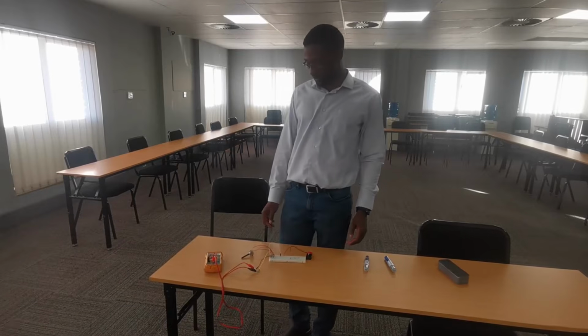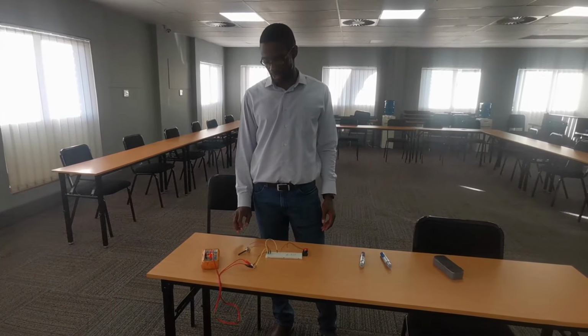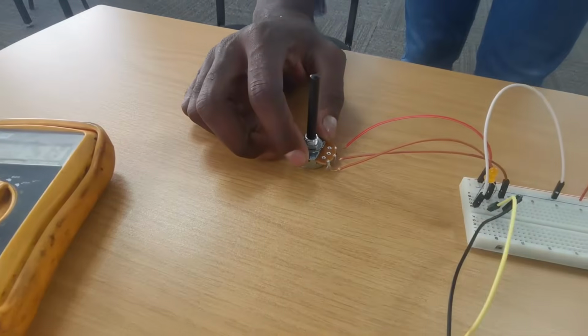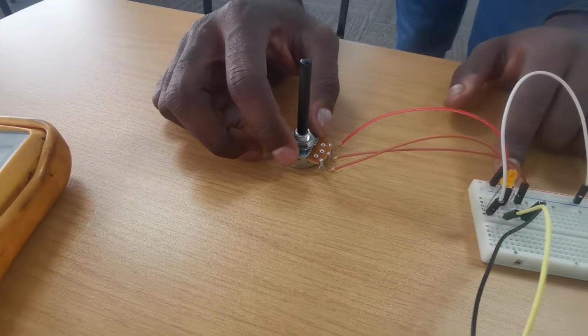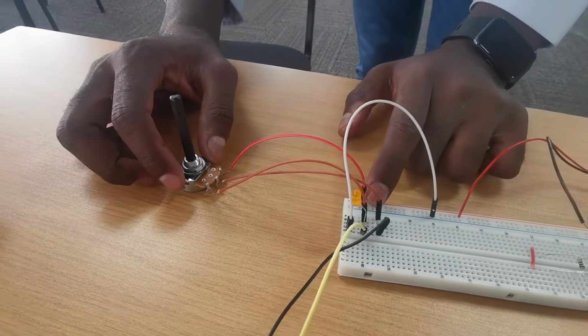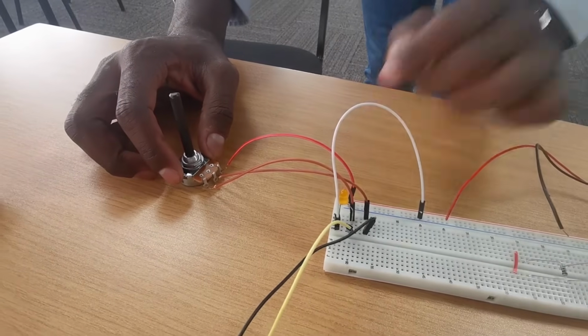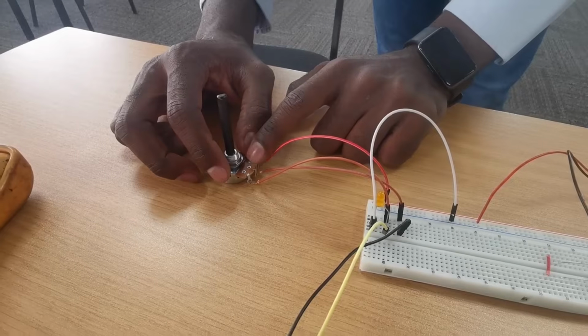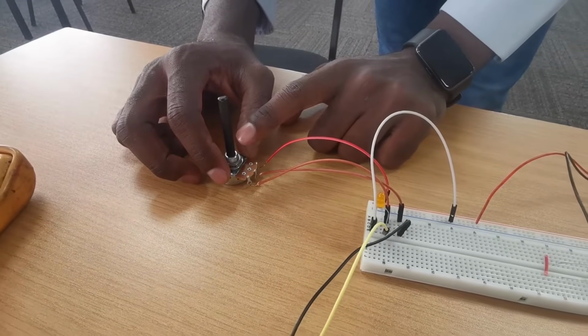Okay, and for those of you that will be using the potentiometer instead of the two resistors, then this is the configuration that you'll need to have. We're just going to look at that quickly. So this is the potentiometer. It's got 3 legs. The first leg should go to VCC, and then your second leg and your third leg become your resistor. So your positive leg of the resistor and the negative leg of the resistor.